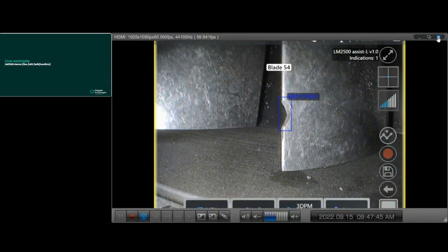So you have the ability to re-illuminate all those indications if you wanted to, offline in the recalled state on the borescope, or indeed via the inspection manager software. You, or perhaps your colleagues, perhaps you're a supervisor to inspectors, or just the inspector, if you wanted to change your mind, have the ability to re-illuminate the different defects that were perhaps originally rejected.